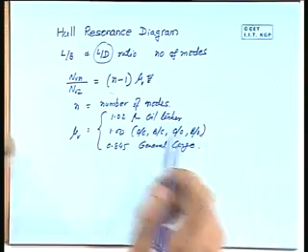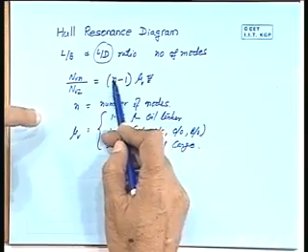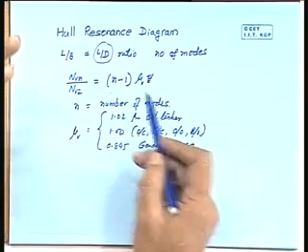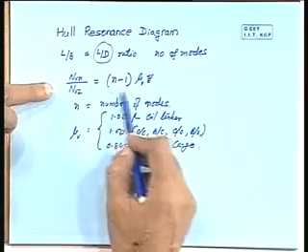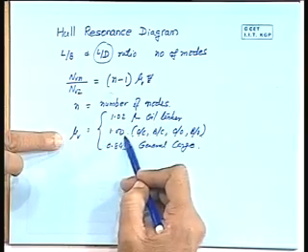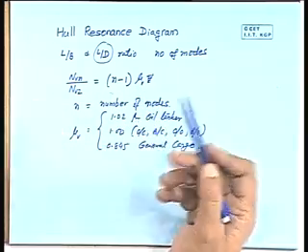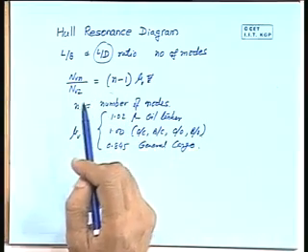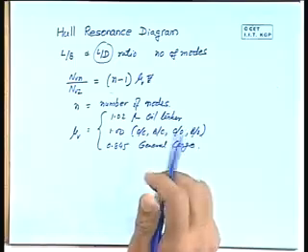What practically one can say is that even if you take n is equal to 2, n is equal to 3 for 3 noded vertical vibration, 3 minus 1 is equal to 2 and corresponding mu v is equal to 1. Okay. So, that means n 3 v is 2 times the n 2 v, double the frequency, and that way 3 times the frequency for the next higher mode, 4 times the frequency of the fundamental frequency for next higher modes, and so on and so forth.